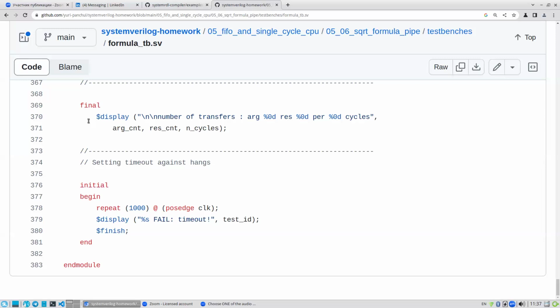The problem with Spartan 3 and 6 is that their synthesis tool does not support SystemVerilog. But Vivado is good enough and can use SystemVerilog. Vivado is compatible with Spartan 7, but not with Spartan 3 and 6.